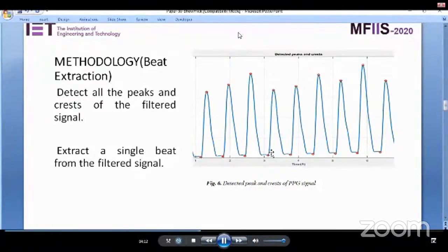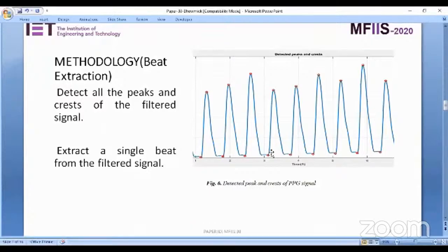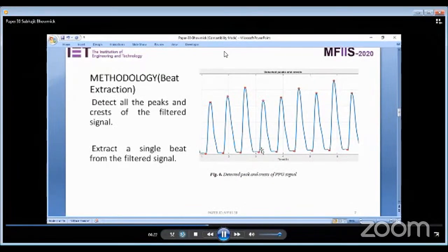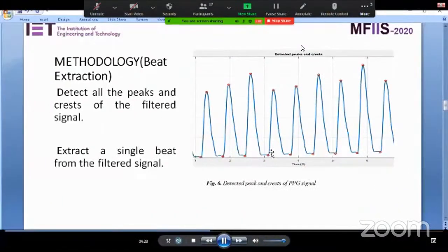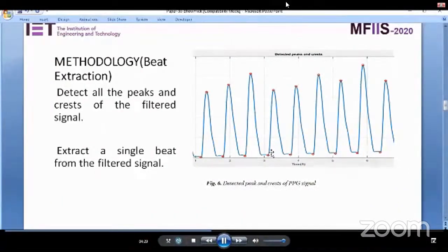The local minima points indicating the foot of the PPG waveform are located in terms of index number, and the corresponding amplitudes are stored into two new arrays. The sample data points between two successive index values form one complete beat of the PPG waveform. The dataset of all beats is stored in a two-dimensional array and in a data file.